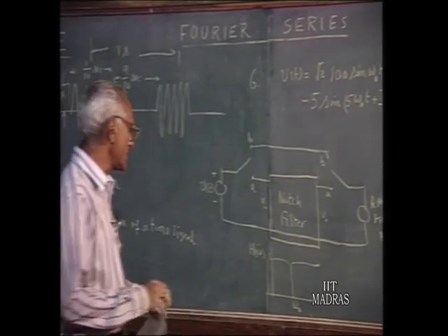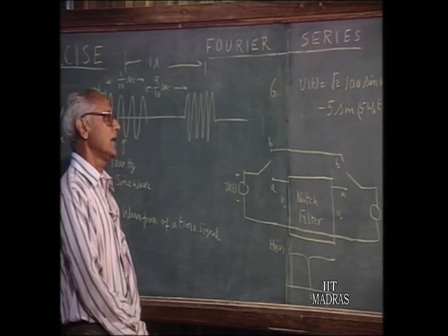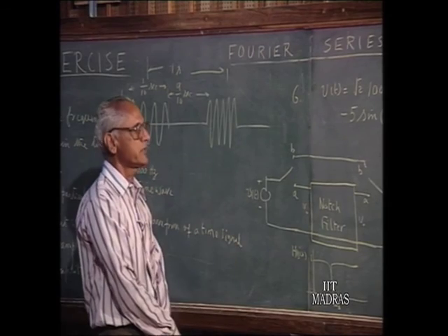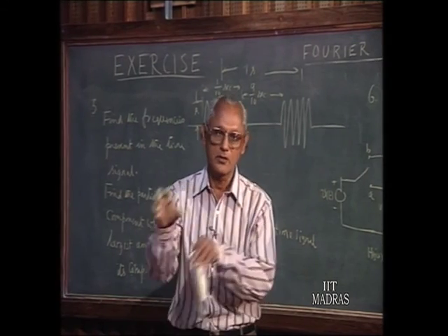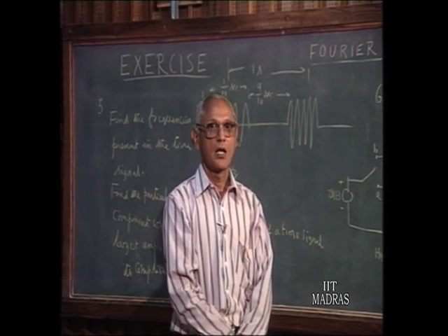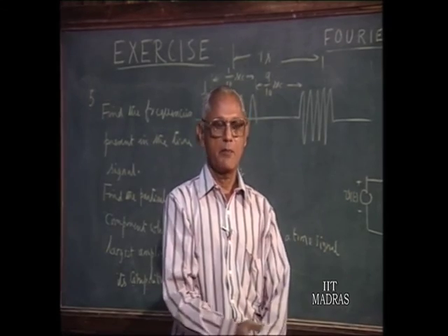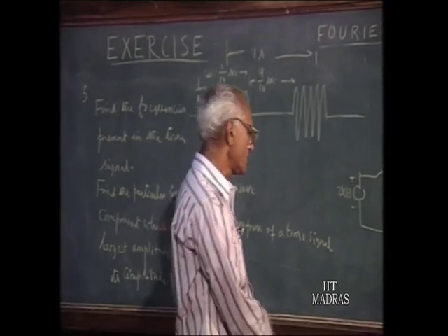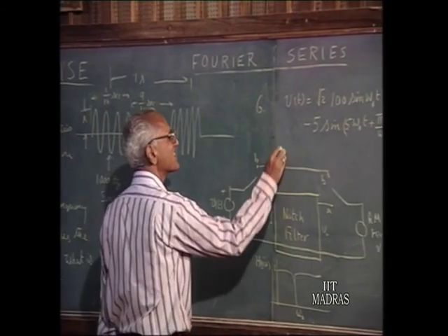So, this meter as such is called a distortion analyzer, and this is used to find out how a waveform which is supposedly sinusoid gets distorted by contamination with various harmonics. So, suppose you have an amplifier system: you feed an input sine wave, and the amplified output must be a pure sine wave, but sometimes the amplifiers introduce distortion, and you would like to measure the amount of distortion caused by a device like an amplifier which may have some nonlinearities. So, this particular instrument, which is called a distortion analyzer, measures the harmonic distortion.